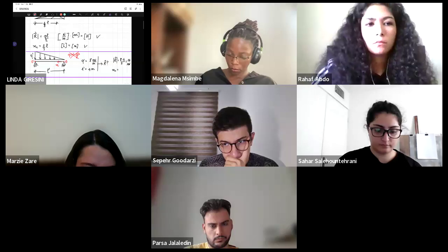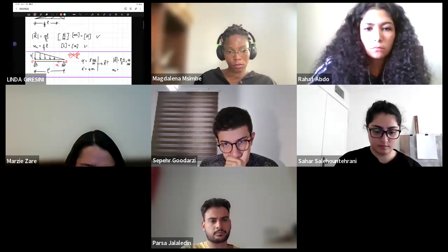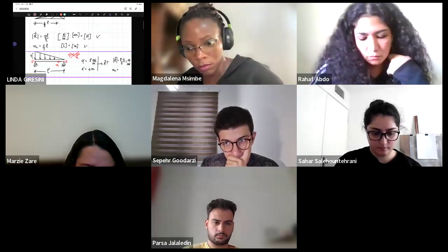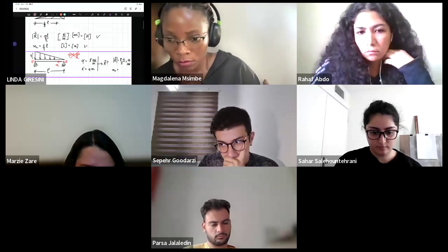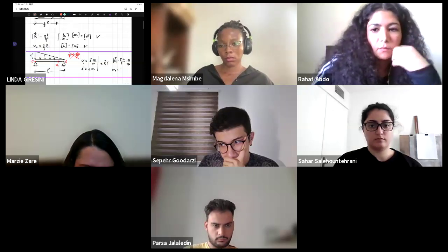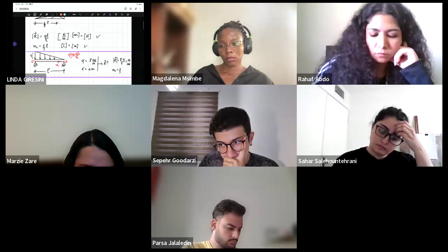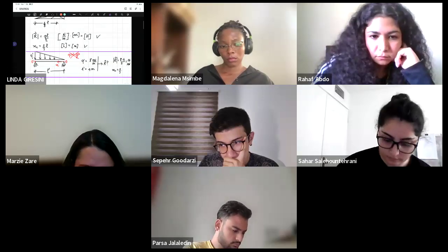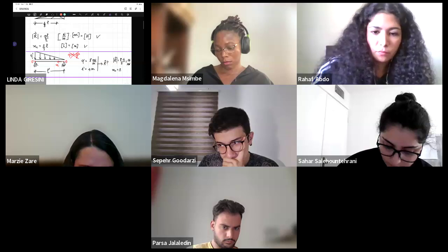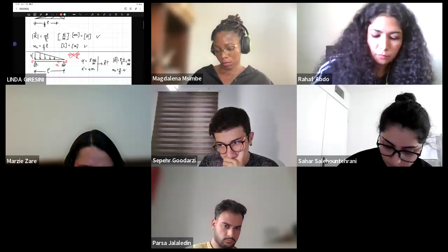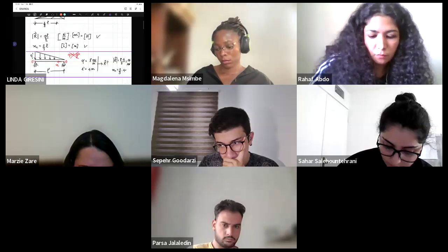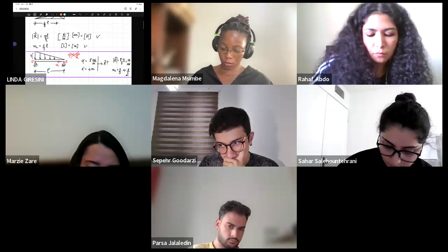So since you know how to solve it, then it's clear. XC with this correct position of your axis, with the origin on the right end, right support, will be 2/3 times length. Length is 4. So it will be around 2 and something, so we can keep it 8/3 meters.